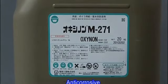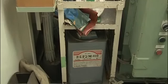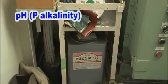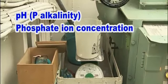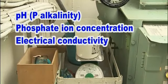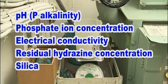Anti-corrosives inhibit corrosion of feed water condensate systems by controlling pH. Proper boiler water quality management means paying close attention to pH or P alkalinity, phosphate ion concentration, electrical conductivity, residual hydrazine concentration, and silica. Each of these items has a standard value that must be controlled.